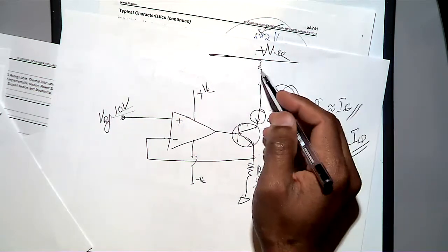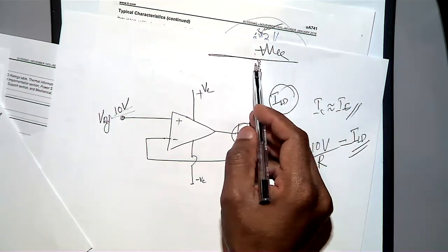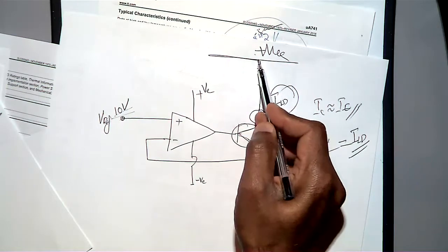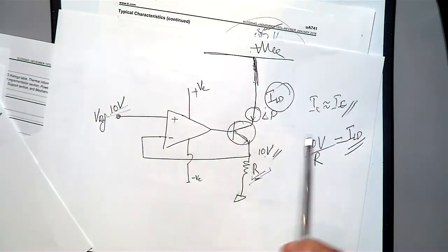Yeah, that's the part I want to. You can connect a resistor here or not. This is just for understanding. Then now the question arises: how do you know this is definitely setting the current using R? There is a feedback. But then we got lots of circuits, like we got a transistor, we got an op amp, we got a resistor, and then we made a current source. So how do you check if it is a current source? For the current source, the current should keep constant. How do you check it?